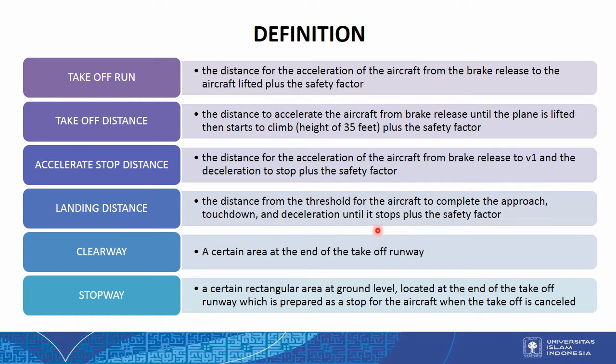Before we discuss more about the runway length, let's recall the definitions that we already learned before, because we will talk about this when we want to design the runway. Takeoff run, takeoff distance, accelerate stop distance, and landing distance, we already learned about these, but maybe under different names, like TORA, TODA, ASDA, and LDA.